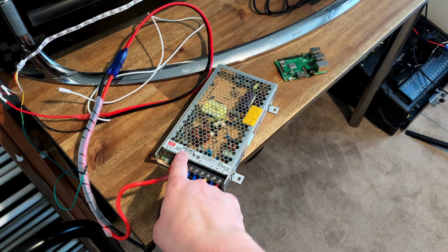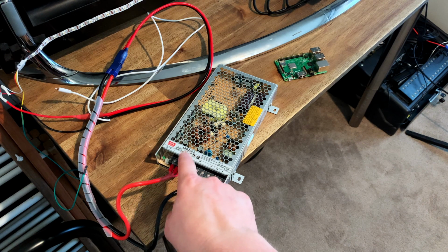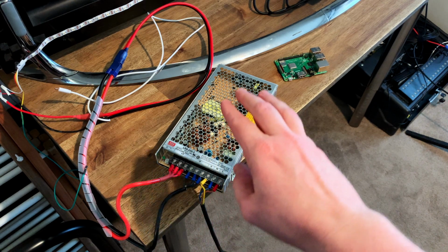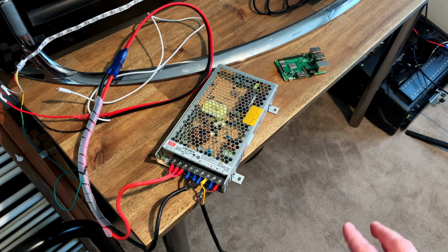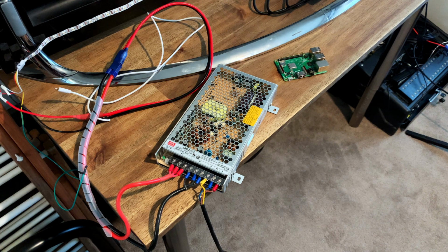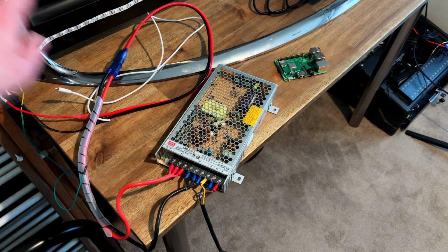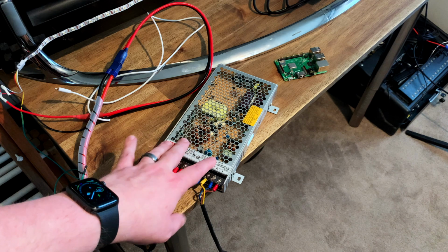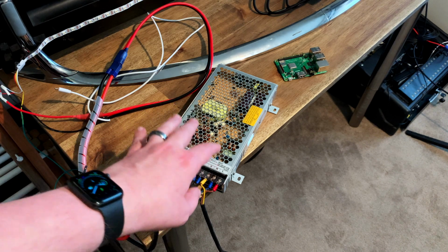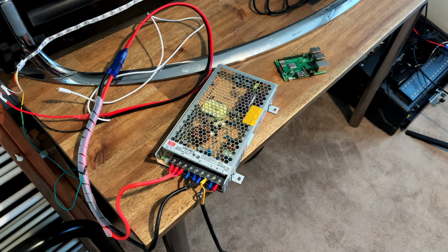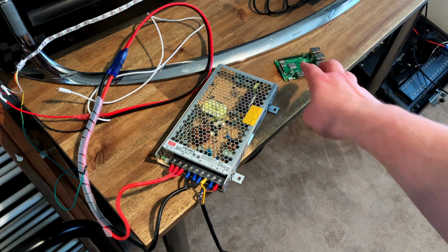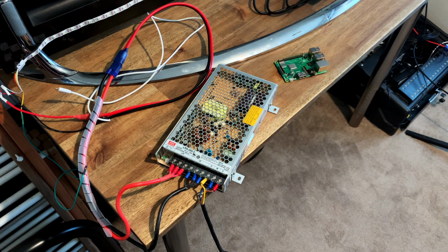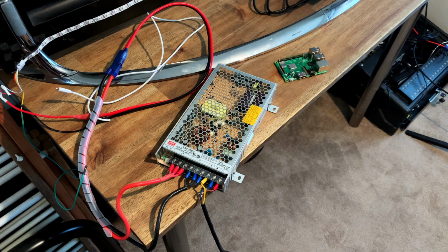It can supply 5 volts at up to 40 amps. This is complete overkill, but it is the best power supply that I had for this effort. I was trying to use an old computer power supply, but what I was finding was that as soon as the LED strips would turn on, the voltage on the 5 volt rail was dropping to below 3 volts when the LEDs came on, and that was causing the Pi to crash, because the Raspberry Pi will start throttling at anything less than 4.62 volts. With this power supply, the voltage is rock solid.